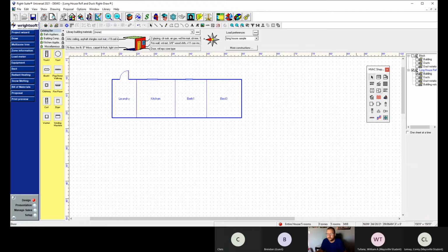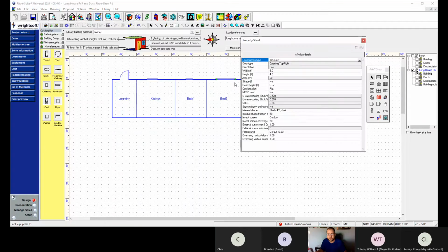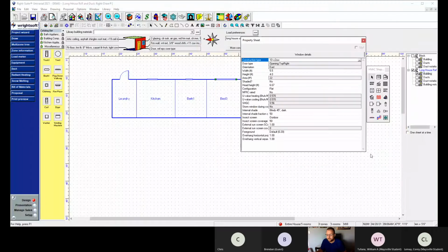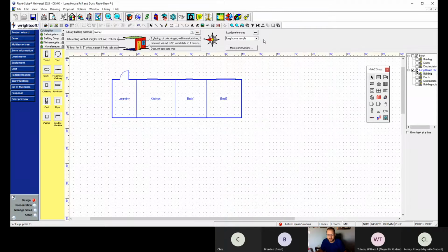It has a window in it, so we'll throw that window in there real quick. I'm kind of doing this quick and dirty, so it may not be exact. It's 66 by 48. So I'm just going to draw it at a certain measurement, and then I can go in here and change it. I don't know what 66 comes to right offhand. It's 5.5 feet, I think. 5.5 by 48 tall. I can change that in these presets or in the specifics of that window. And if it was a different type of window, then I could select this top one and go in here and select the difference. For now, I just made one window that was my A window. So all these are A's. There are a couple B's on the front, and we'll change those. Everything else should be standard based on what I already set up.